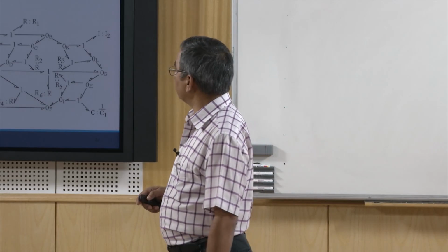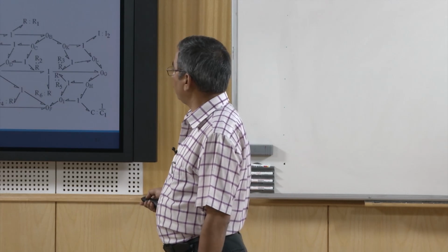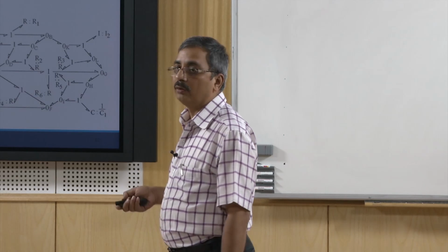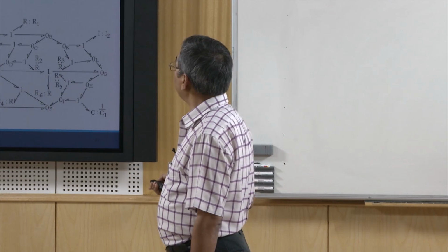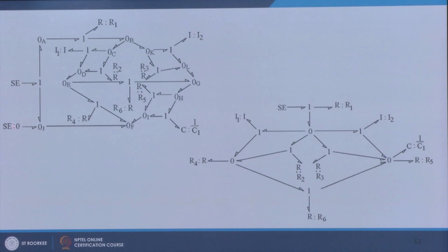Now, what we can do is apply the ground here. So, SE is equal to, say, 0, I am applying here, and let us see how this bond graph gets reduced. So, in the next slide I am applying SE equal to 0 here. Now, you see that when this is subjected to 0 volts, the effort in this one is 0. Similarly, this is a 0 junction, so the effort in this one will be 0. So, this bond will vanish, this bond will vanish, this bond will vanish, again this is a 0 junction, so this bond will vanish, and this bond will also vanish, and again this is a 0 junction, so this bond will vanish as well as this bond will vanish.